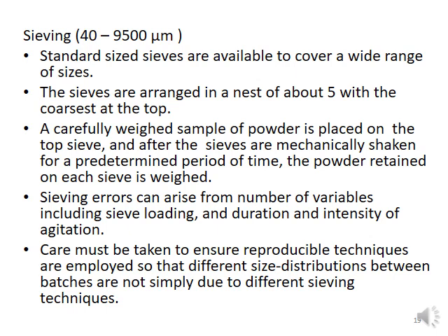For example, a change in the agitation method might change the particle size, and this might affect the results obtained using the sieving method. Usually, as I mentioned before, it is used for particles within the range of 40 to 9,500 micrometers.